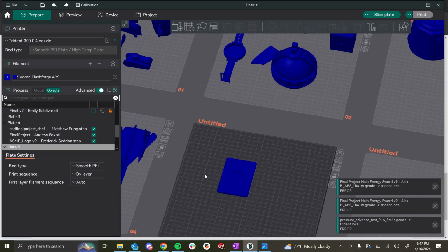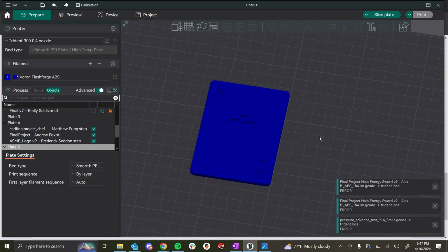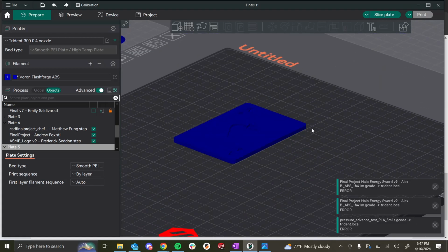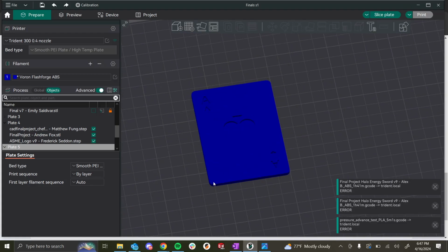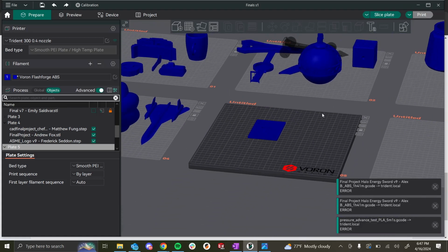Right here, this print is very easy, right? It's very flat. I'm not saying you have to do something this simple. This is a playing card, if you can't tell. But you can see it has rounded corners, so the rounded corners make it harder to lift and curl. So that is a good feature to have.